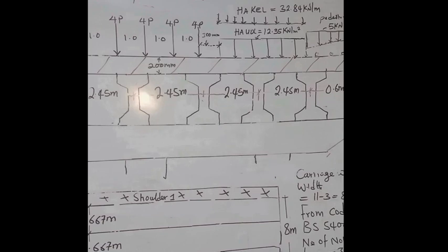Number two, we'll have the sectional modulus and the moment of inertia of the I section. Equally, we are still going to work on the composite section. Remember, the bridge is made up of the composite part, which is the bridge deck of 200 mm, and we are going to determine the moment of inertia of the composite I section, and from there we can begin to solve other problems.